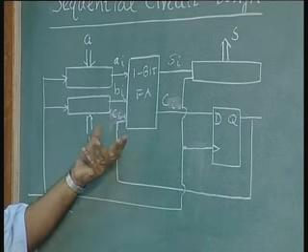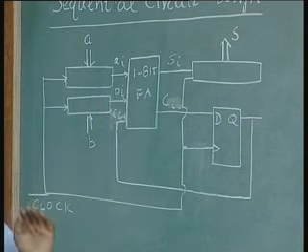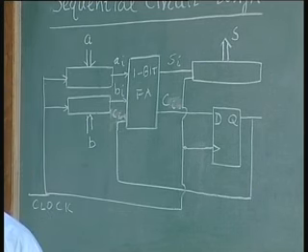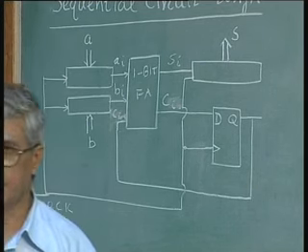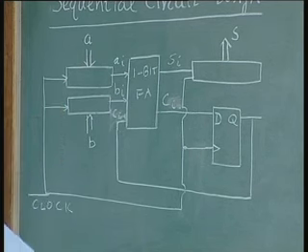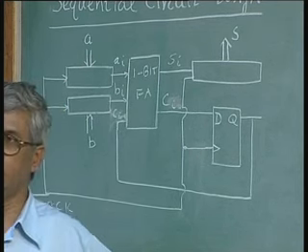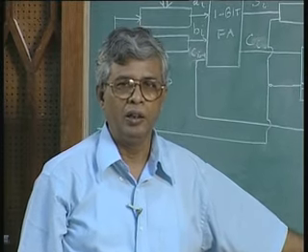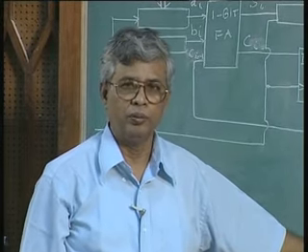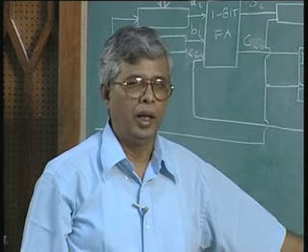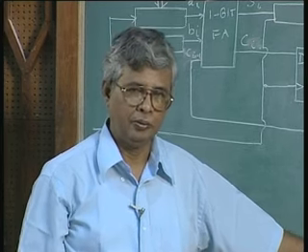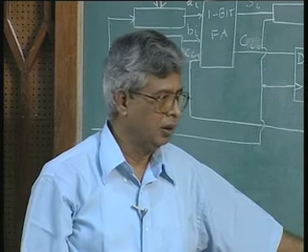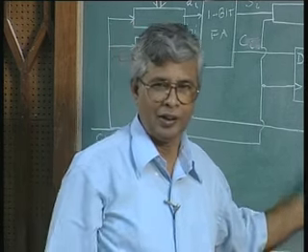I just brought this up because today full adders are so inexpensive. You know, a full adder consists of 2 exclusive OR gates for the sum, and three 2 input AND gates and a 3 input OR gate for the carry, and it is not a huge hardware, and you can multiply it any number of times in order to carry out a large addition, plus the fact that this also delays the addition process.